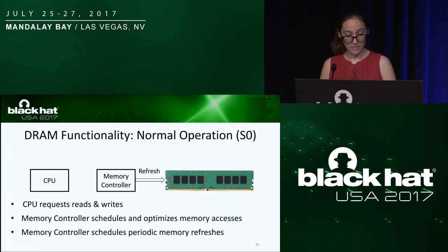And also, the memory controller is responsible for scheduling periodic memory refreshes, because the way that the data are held in the DIMM is by having a small electric charge in the capacitors that are on the chips there. But this charge leaks over time, so the memory controller needs to do refreshes in order to actually keep the contents of the memory there.